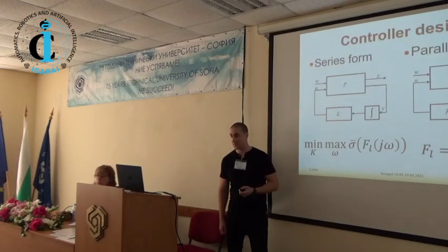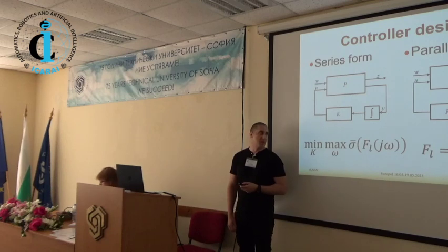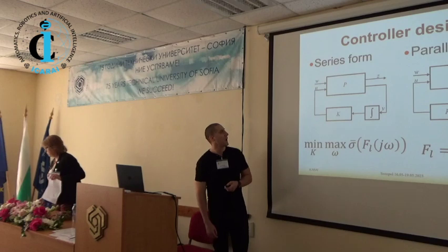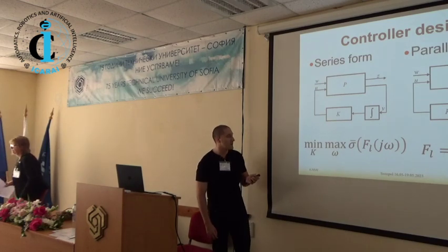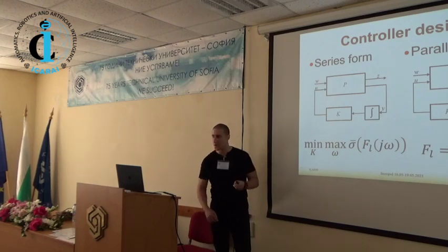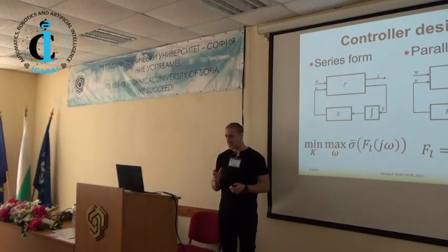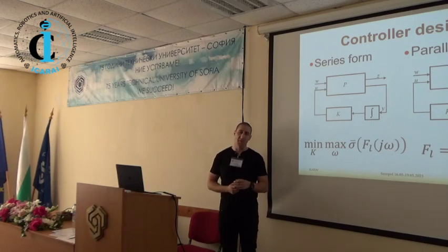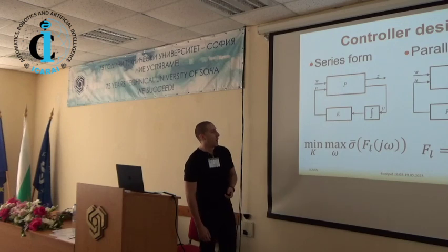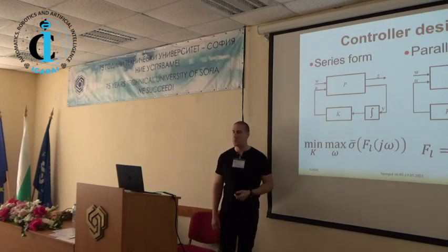The design of the controllers themselves. We are using the well-known mixed sensitivity S/KS structure with 2 arrangements of the integral part, one in series form and one in parallel form, to check if there will be some differences in the performance of the system and if this somehow will help in the reduction of the controllers. We are using the shaping filters to shape our frequency responses in a way to achieve some performance.